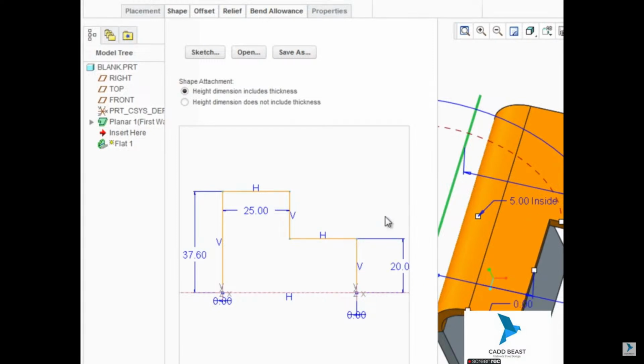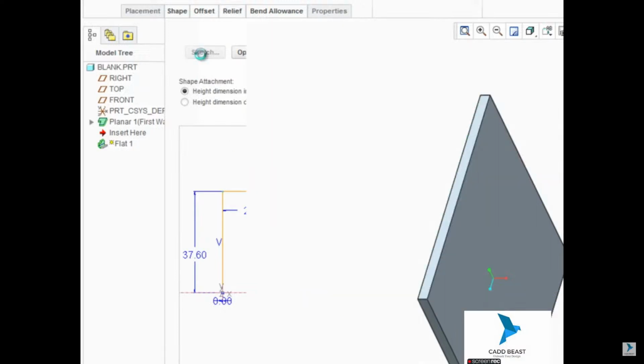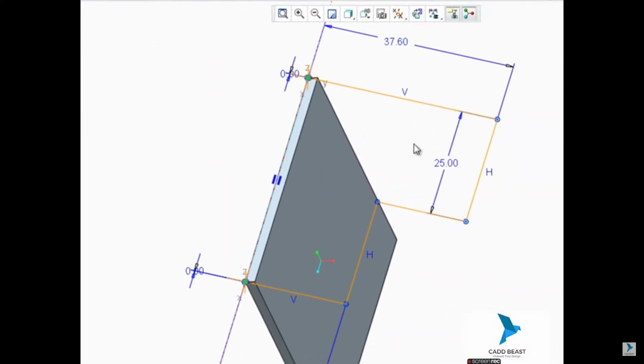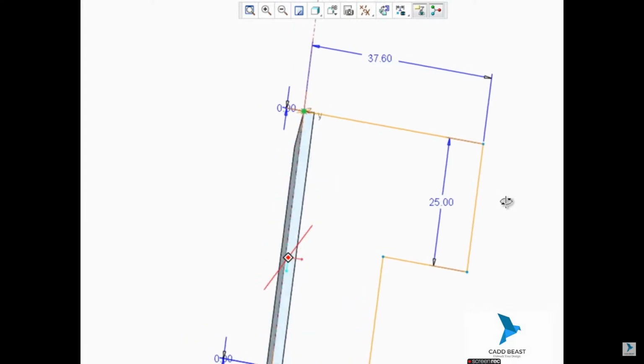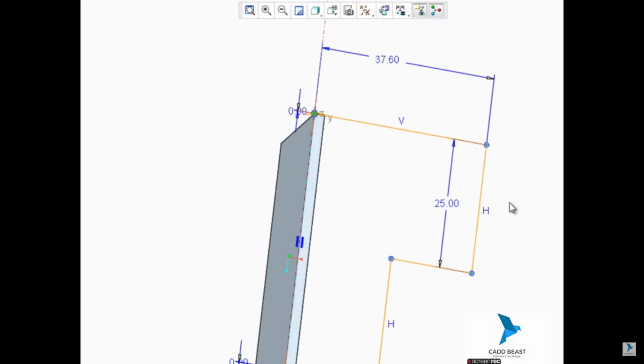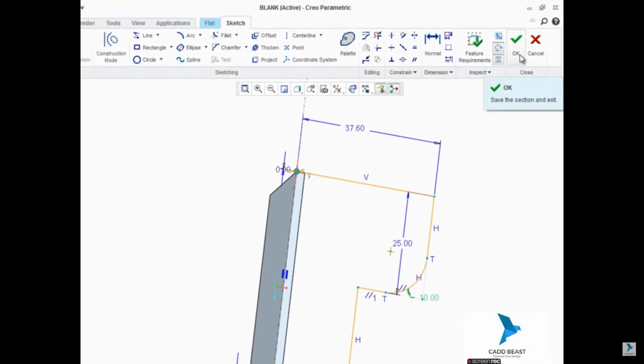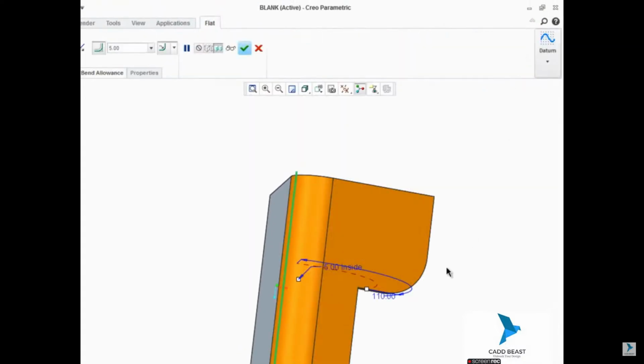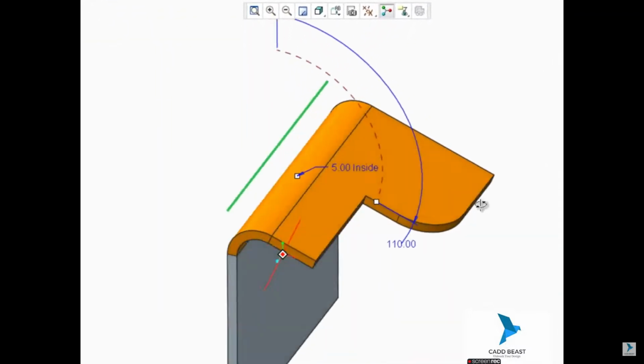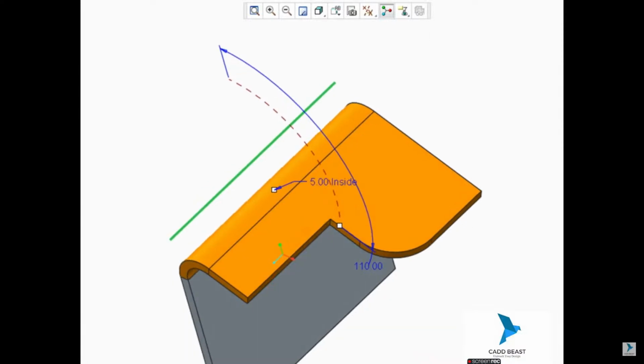To create a user-defined shape, enter Sketch mode by clicking Sketch from the Shape tab. We can see the sketch of this wall, and we can edit it, like adding a fillet to a corner of the wall using the Circular Fillet tool. Creo Parametric provides you with several convenient and intuitive starting points to quickly create secondary flat walls, and makes custom designs simple too.